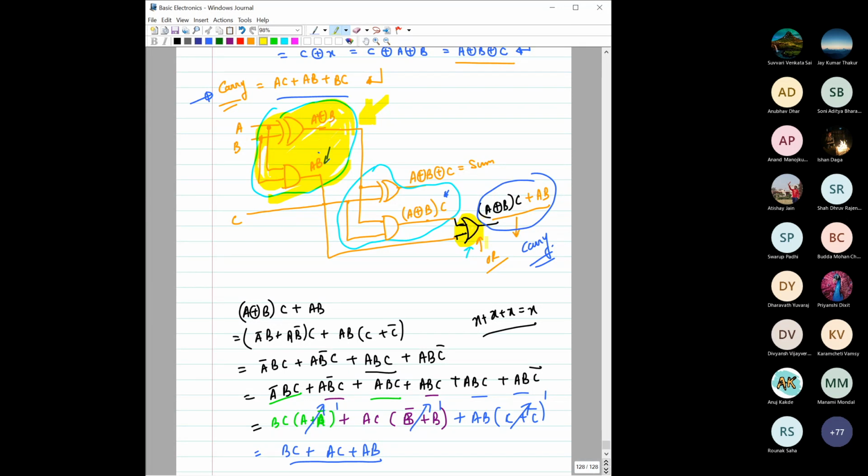Okay. Will the XOR gate give you the carry? Have you checked it? Sir, even if we add them, there will be no carryover of the carries. Both of them cannot be one. Only one of them can be one at most. So even if we use an XOR gate, I think we should get the desired output. Okay, that you think, right? So could you please check it using pen and paper and tell me in the next class? Yes, sir. Okay, so please do a check.